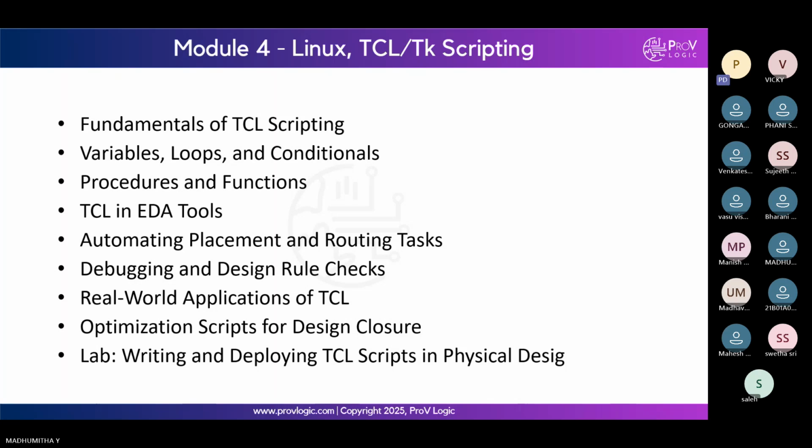If the latch is going to turn on and the data is going to be latched for the positive level, it is called a positive level sensitive latch. If the data is going to be latched for a negative level, and it is transparent for the positive level, it is a negative level sensitive latch.